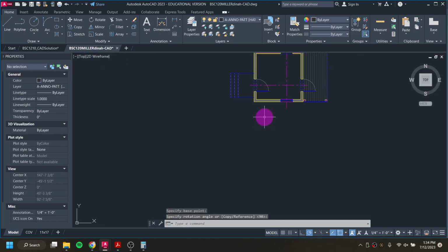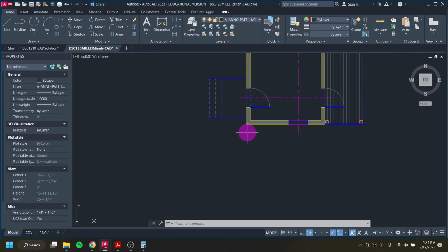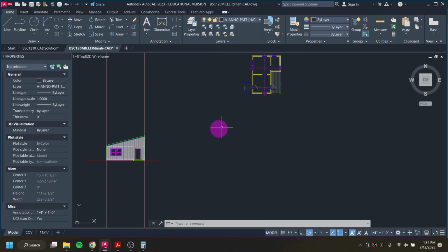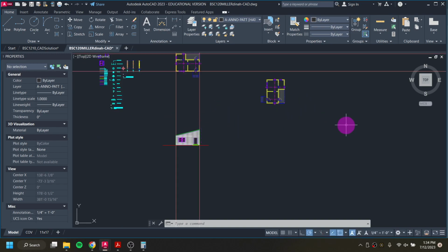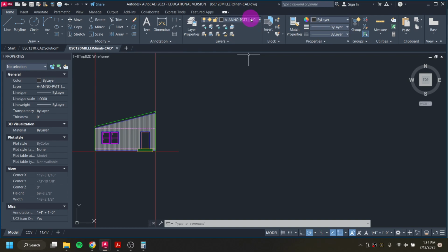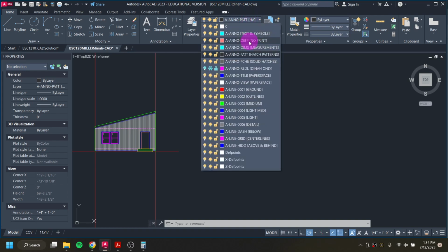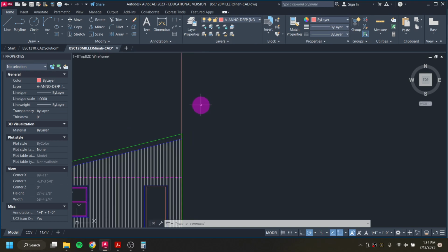What this is going to allow me to do is, again, trace some of those rays out so that this way I don't have to measure anything out too much. So I'll do some rays from this view here, again, to just stop me from having to measure, and I can use some guidelines to build out my east elevation. So I'm going to switch my layer to Anno Def, so that way I'm in the no printing def point layer, and I'm going to draw a ray,